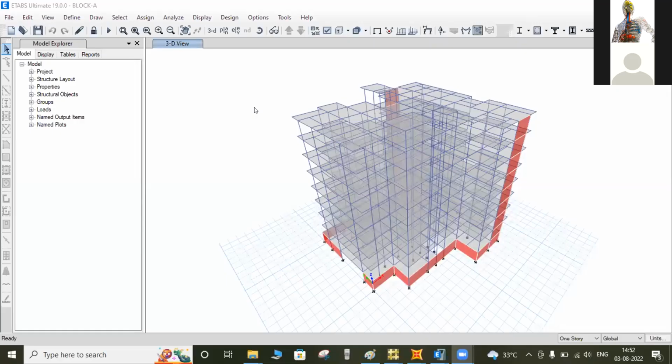Basically, for this structure, initially we explain all types of analysis. First of all, we are discussing the modal analysis as per the self weight, with no external load. We consider self weight as a free vibration. The structure gives the response in a free vibration condition. We can identify the particular time period to complete a particular oscillation. So the first analysis is important. Modal analysis is efficient, and moving to the external loads, it is also efficient for dynamic analysis, and also efficient for torsional irregularity.